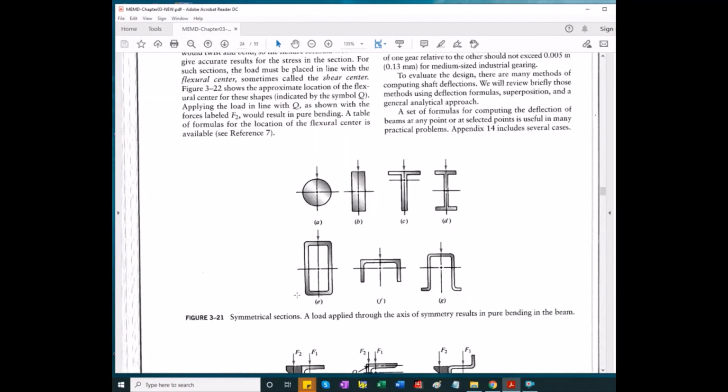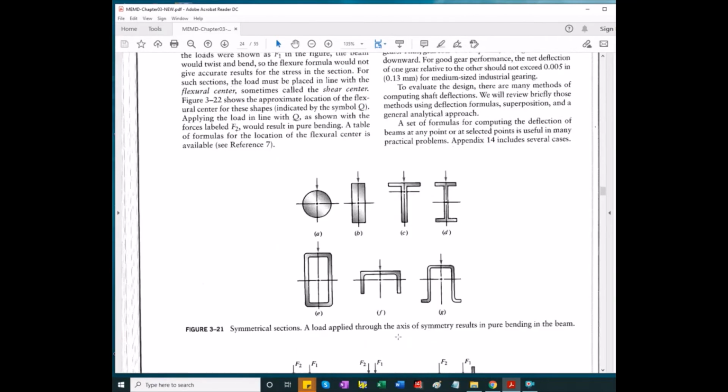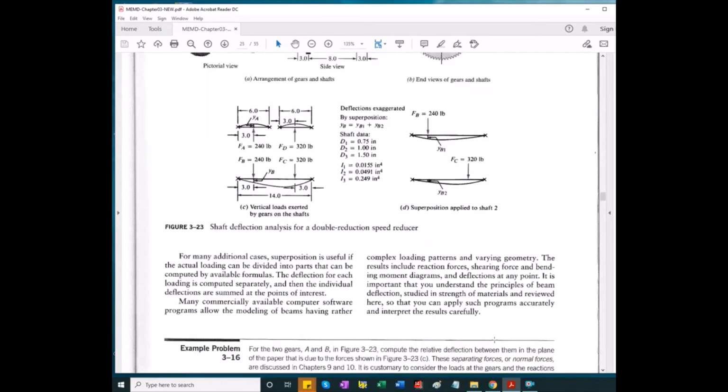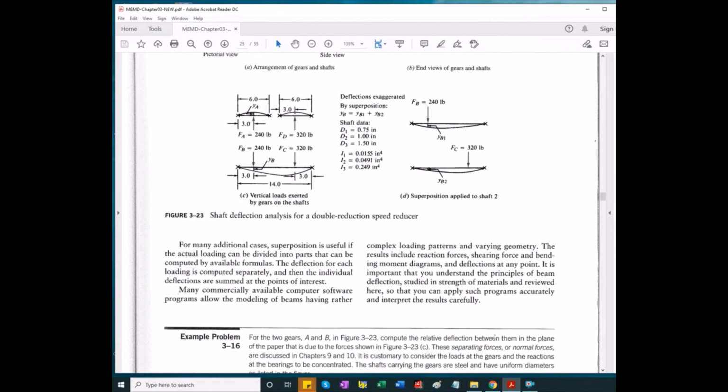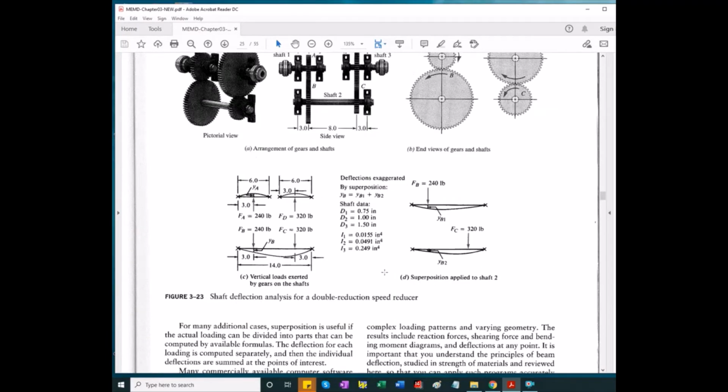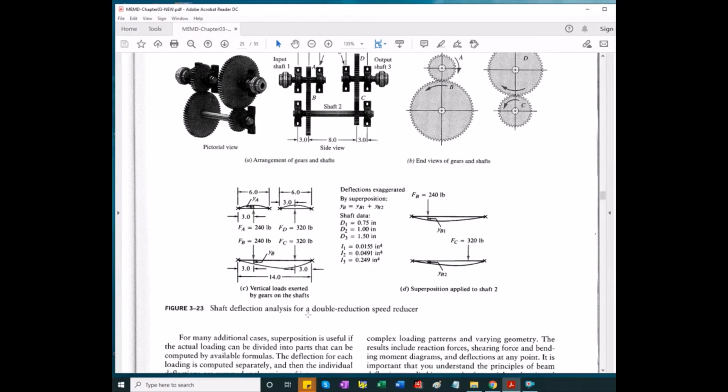The book lists the amount of linear deflection on shafts. With deflection comes change of slope. So if you have a gear, there's also, the book does not discuss this, but as the shaft deflects, the gear will follow locally and will align itself with the tangent.